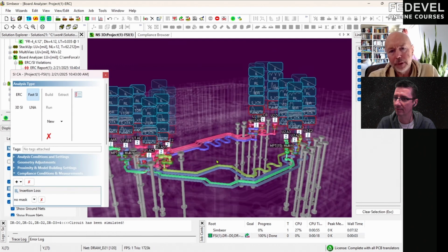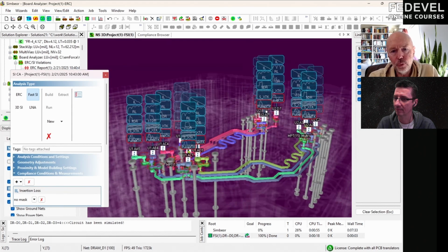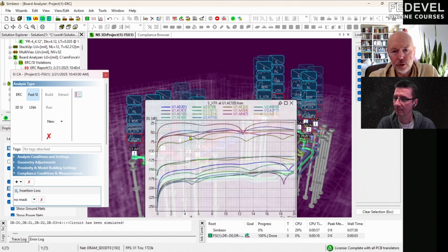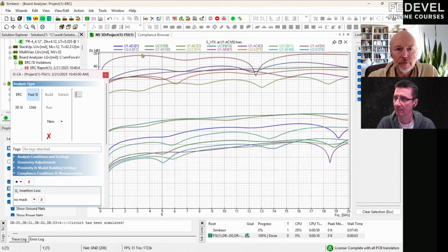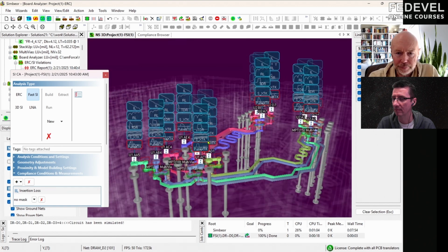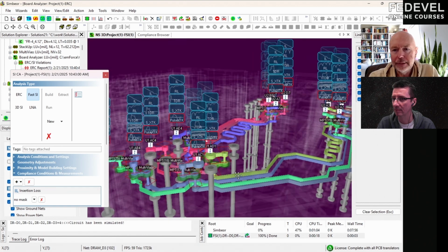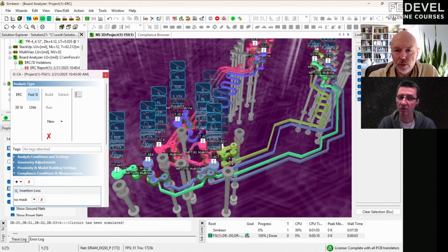If you put a compliance metric in the form of pulse crosstalk. And this is S parameters of crosstalk. So for instance, this aggressor, you can see it's about minus 20. It's probably the closest trace to this particular link.